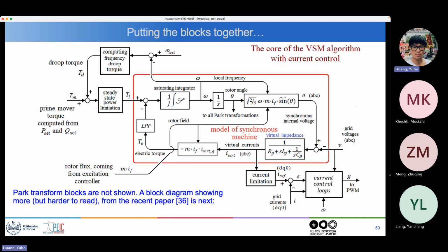I think that I have exceeded my time. I have many more slides, but I can give you the slides if you want. I don't show any more slides now, I just tell you that there are various games that you can play with virtual synchronous machines connected in a grid. One important such game, which was Florian's main topic in his thesis, was virtual friction. Virtual friction means that you want to prevent the generators from oscillating against each other, the inter-area oscillations.